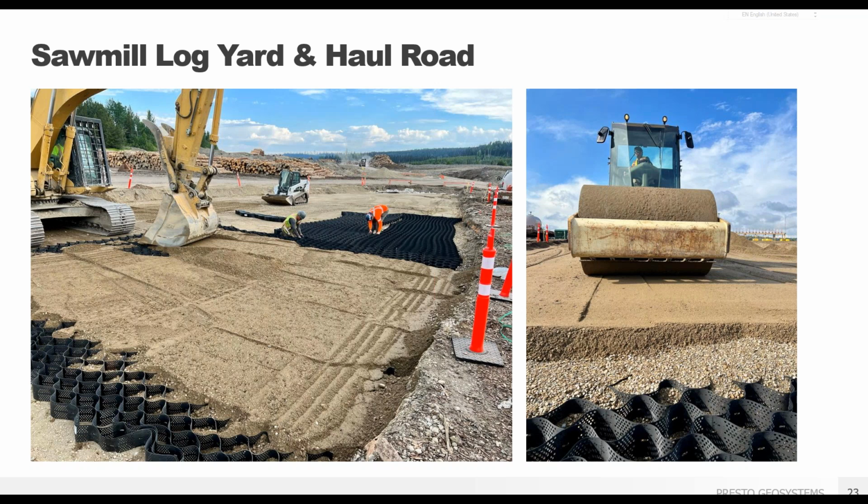Here we also see a good technique tip with crews working in parallel. On the far left, placing of the infill by the excavator, while workers expand and connect the new sections of GeoWeb. Far right, we see the roller compaction of the infill. Having a crew with well-defined roles allows this kind of work in parallel, an installation best practice, and makes for an efficient installation all around.